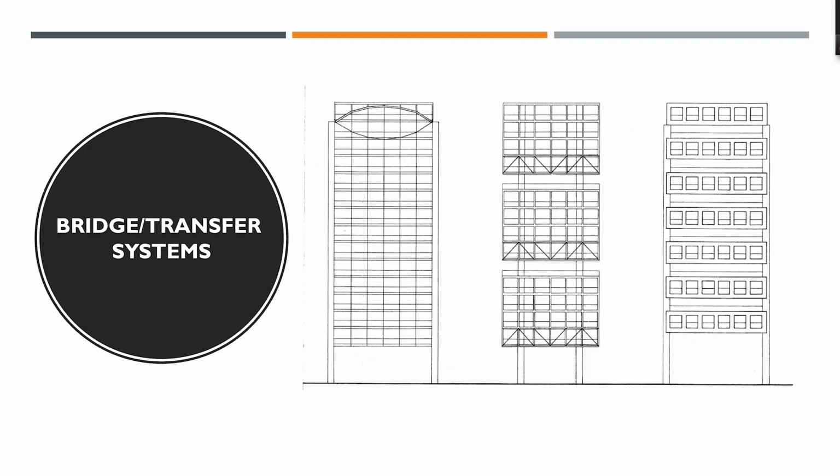This is very common. You would provide these transfer slabs or transfer girders in many places, because this may be the swimming pool area or there's a community area. Many buildings have these nowadays. So they bring the columns, then they want an open space, then start again. We have done several buildings of this kind where they break every 15, 20 floors. There is an atrium, there's a high floor with trees growing there and pools and whatnot. Okay. And then start again.